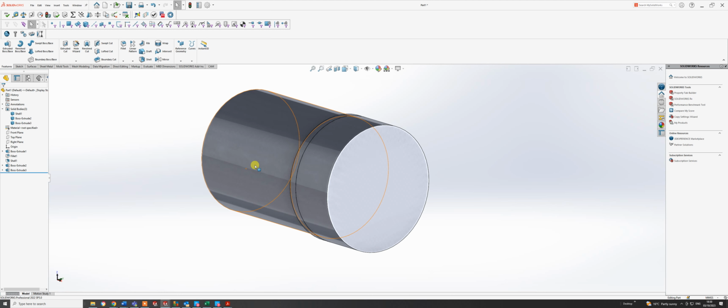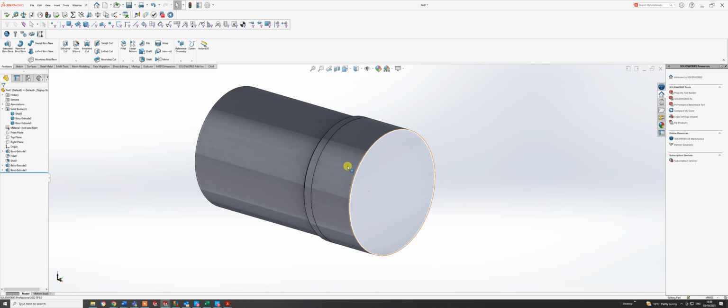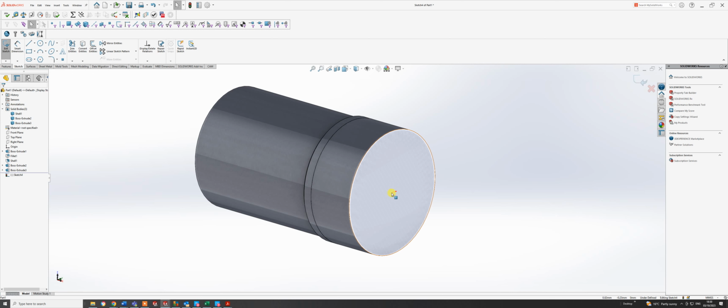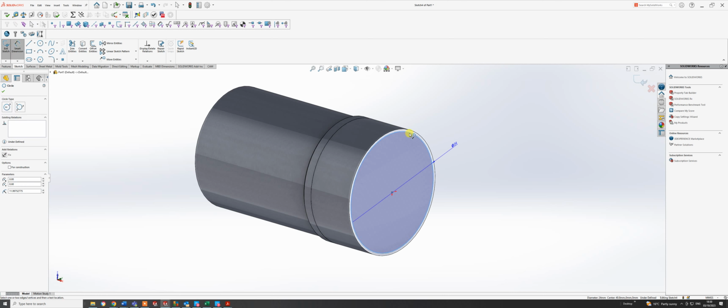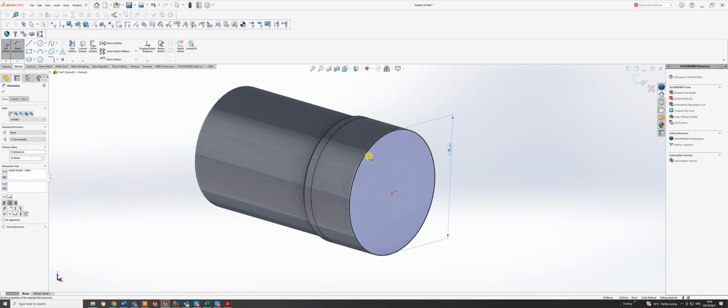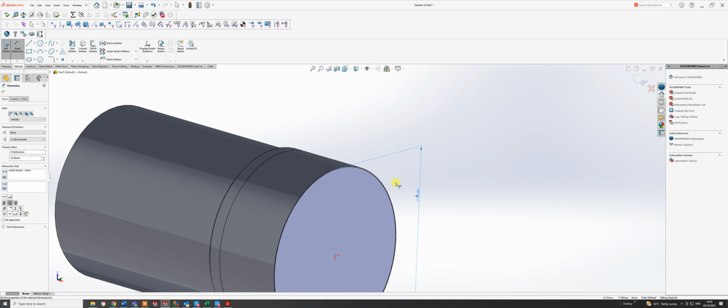Okay, I now need to do the last little bit of the gearbox housing. So I'm just going to go to sketch, click on that face again because I'm going out, and again I've got my little UCS. I'm going to go to circle, pull it out, slightly smaller, just a fraction, actually 0.1 of a millimeter. Go to smart dimensions, click on the outside. Okay, and I know that is 24.8, and you'll notice it goes, and you can see that's 0.1 of a millimeter.